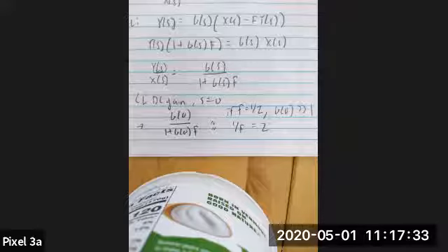And then also, if we put in a low frequency around 0, then we can see what the gain would be. And if this is a typical single pole system, what I'll derive a little bit later on is that a closed loop system is also still going to be a single pole system, but the bandwidth will be increased.